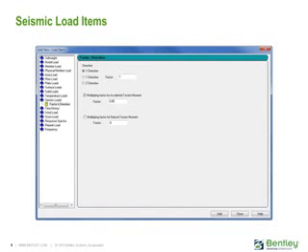In this video, we will complete the process of applying our seismic loads to our sample structure by using seismic load items. Our process is that we will be applying our seismic loads in the positive and negative global axis directions. We will learn how to incorporate orthogonal effects into your structure if required by your building code. And we will also learn how to complete this process by specifying some analysis and change commands and also the SET NL command.